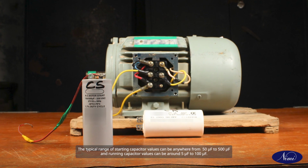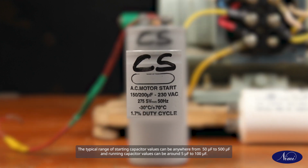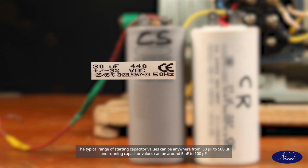The typical range of starting capacitor values can be anywhere from 50 microfarads to 500 microfarads, and running capacitor values can be around 5 microfarads to 100 microfarads.